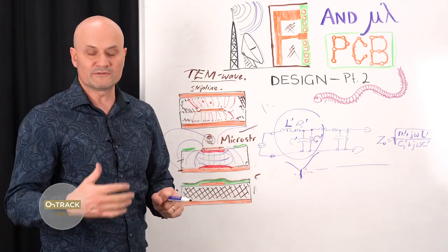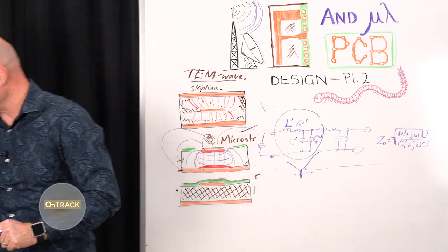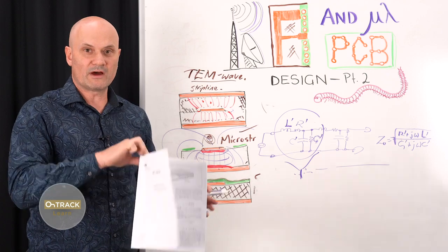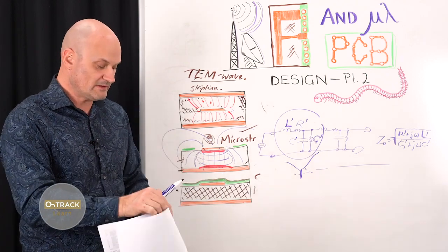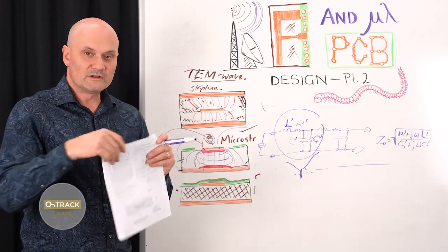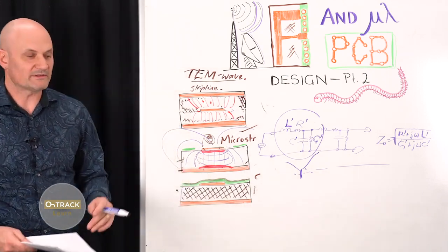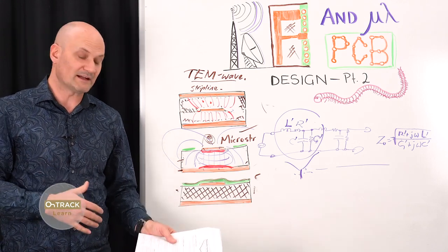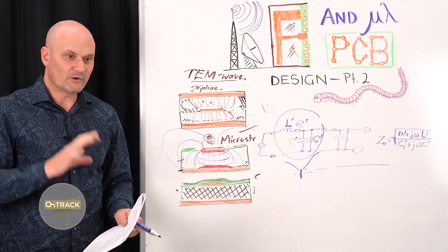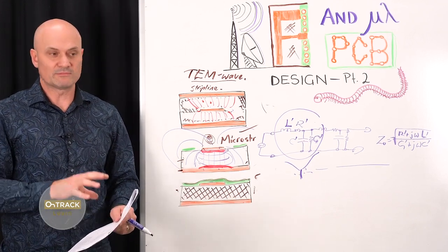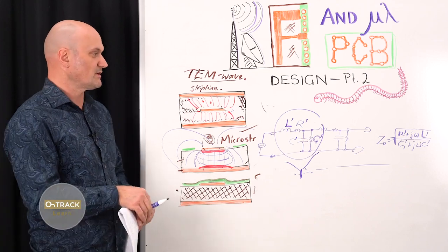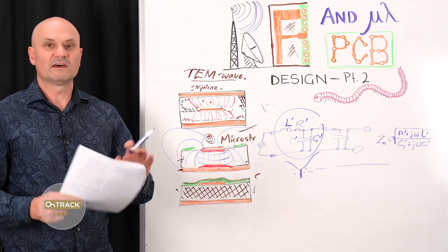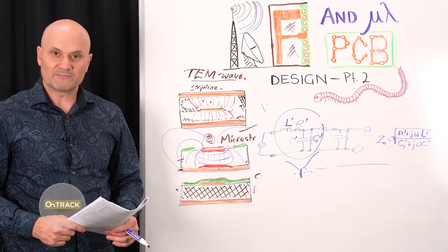And others have improved, so Jensen, what are some of the other names? They're all here in this really useful guide, IPC 2252. So basically, all of the impedance calculators you would find, there's a number of free tools out there, and there's impedance calculation built into Altium Designer. They all stem from the work that's been done and distilled into these sorts of documents. And so rather than fill the board full of tons of mathematical equations, I would say check your CAD tool.